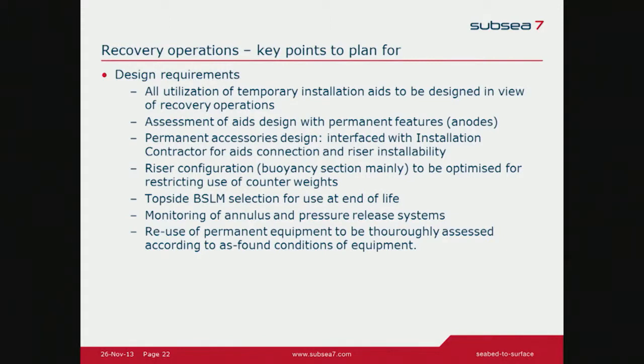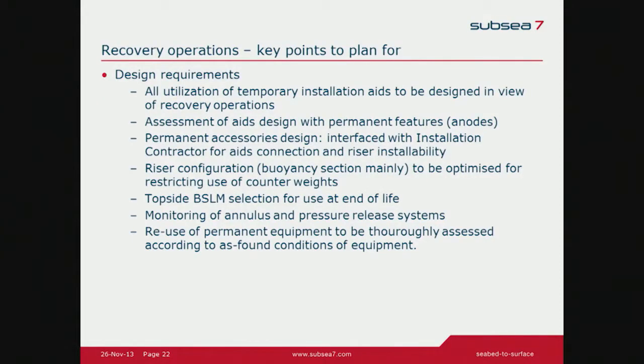Riser configuration is usually a challenge because the configuration is given at an early stage and always changes through the project. At the end, we always end up with much more buoyancy uplift than at the start of the project, which usually impacts schedule and methods. Topside bend stiffener latching mechanism selection needs to be done with recovery in mind again.